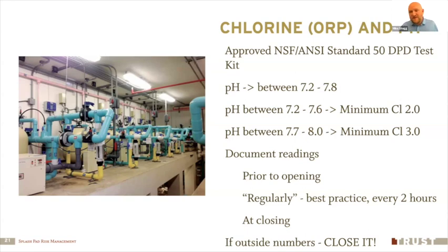Then you don't test again until 7 o'clock at night or 8 o'clock at night. Okay. There's a lot of gap there where you can have chlorine or pH or things that are going funky in the chemical room. And you've got bodies in the water. You've got sunscreen. You've got things going on. We have to make sure that our chemicals are in balance the entire time we're open.